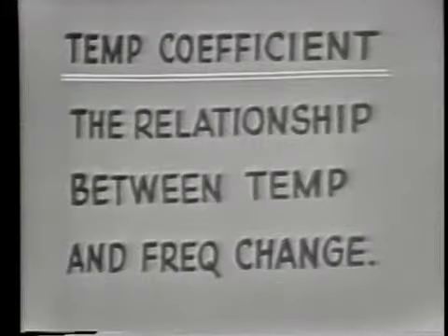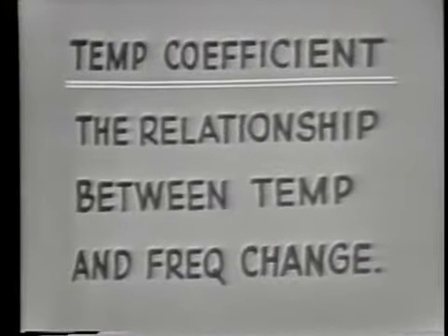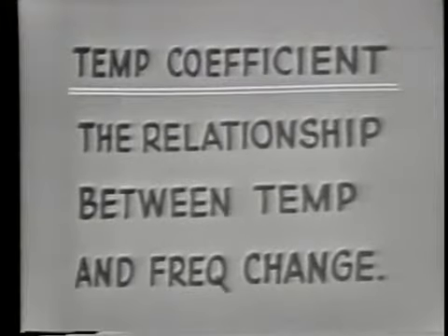Now, another characteristic which will be different for the various crystal cuts is the temperature coefficient of the crystal. The temperature coefficient. Now, this is a new term, so let's define it. Temperature coefficient is the relationship between temperature and frequency change.